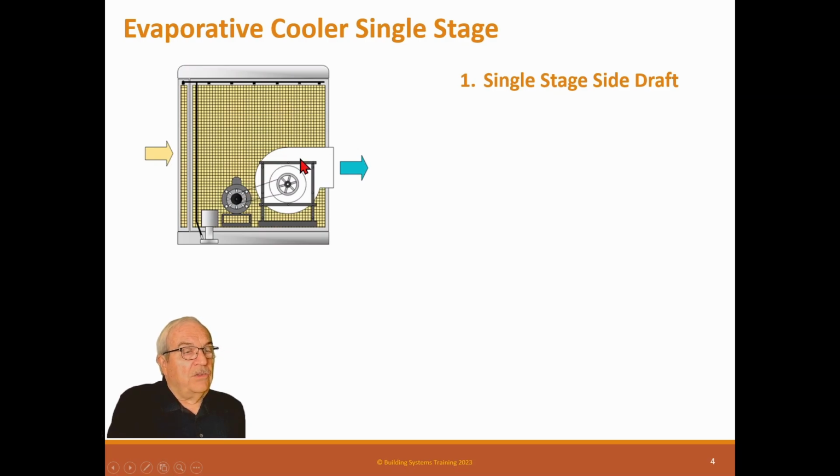The other thing with evap coolers, their problem is maintenance. Maintenance is very high on them. So what we try to do is dump this water every once in a while and bleed it, so we keep the concentration down in this pan. Because as it evaporates, the water coming back still has all the solids the other water had. So this pan begins to grow in solids, and it'll get real high. So normally we'll drain every so many minutes in a day. We'll drain this down when it's pumping, so it fills up with new water, and then we stop it.